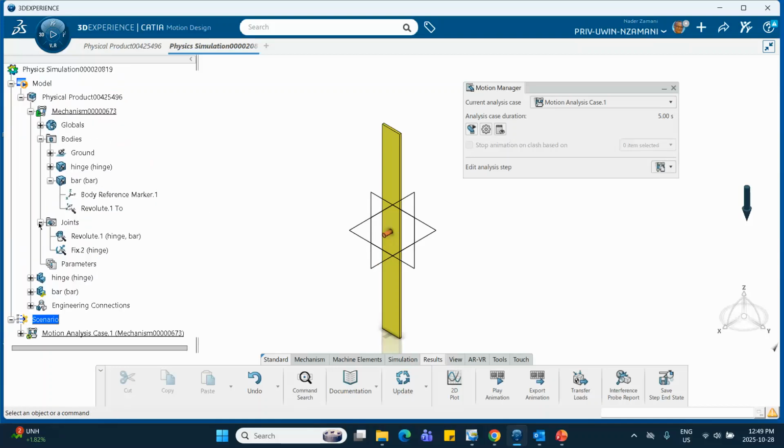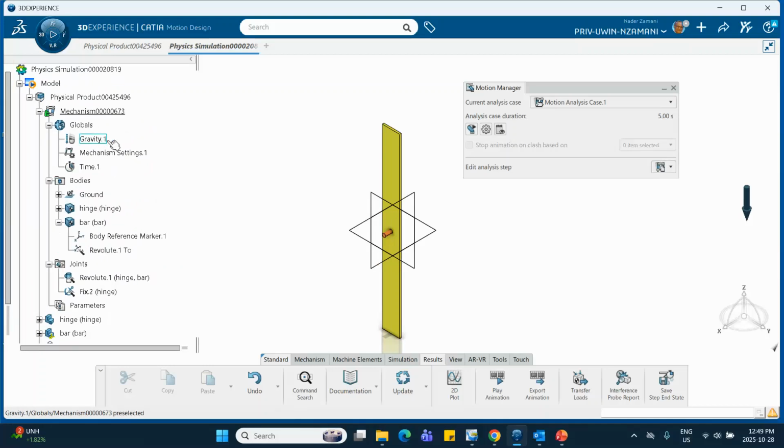What else do we have here to show you? Yep, gravity has been applied in this particular problem. Gravity does not play a role because the angular velocity immediately before impact is zero. After impact, it's going to be something that we're going to calculate, and g doesn't come into the picture because the spring does not have an impulsive load. Gravity does not have an impulsive load either. Okay, so let's go ahead and do this.